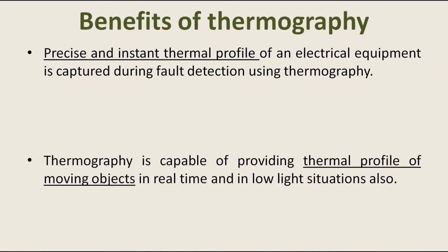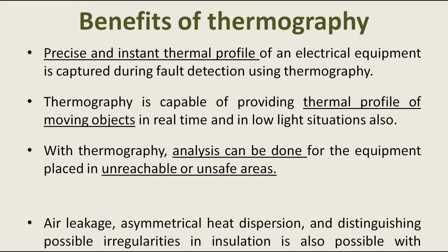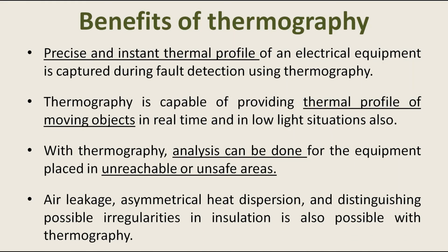So let us now summarize our learning. The benefits of thermography are that a precise and instant thermal profile of electrical equipment is captured during fault detection. Thermography is capable of providing the thermal profile of moving objects in real time and in low light situations also.